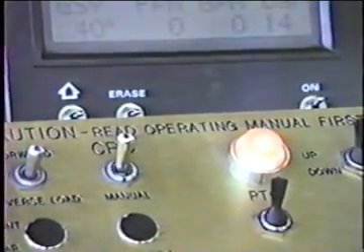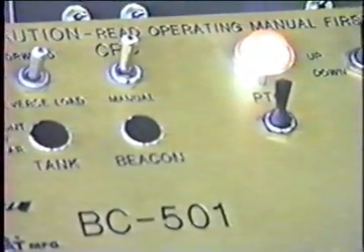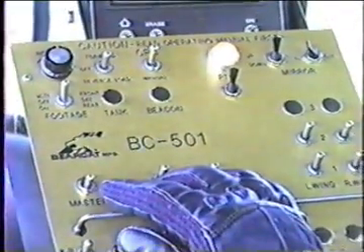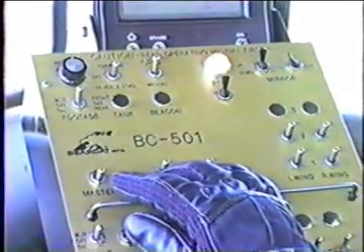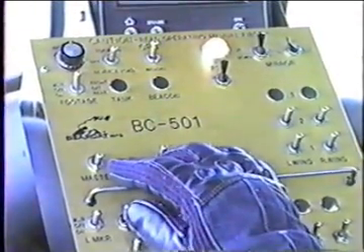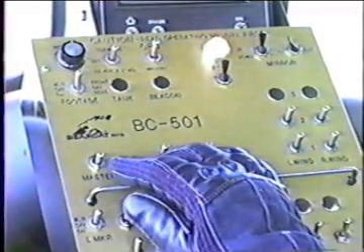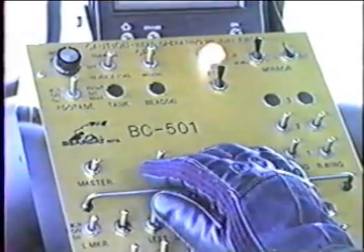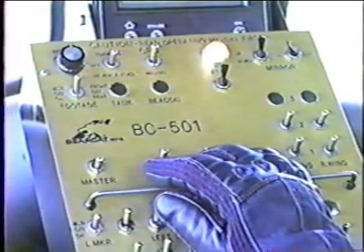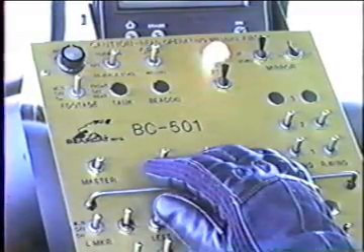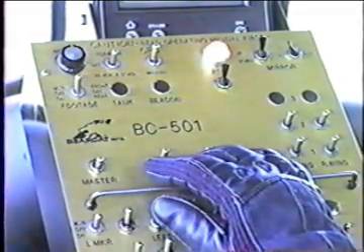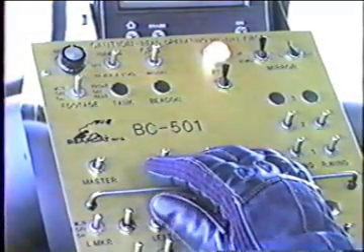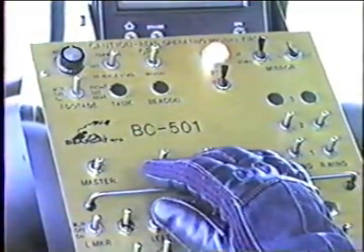It would have what we call computerized rate metering, and that is the computer would see the rate. It would see the travel speed, it would see the bar width, and then it would calculate those together, and it would also see the GPM. It would calculate those three together and tell us what the GSY was, and we would have to then control the pump to where the GSY read what we wanted, and we would do a dry run in order to get set up that way.